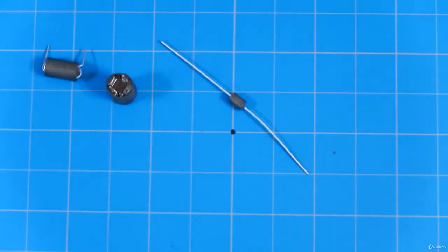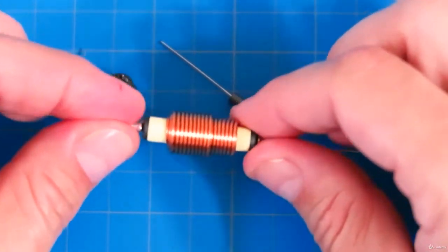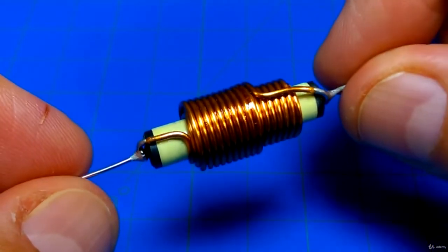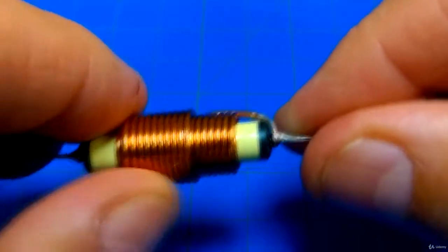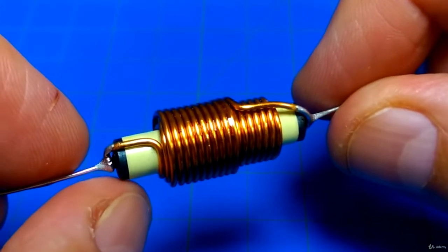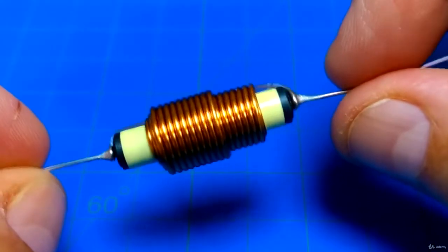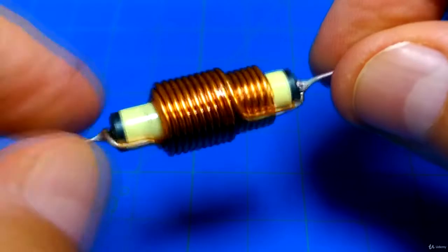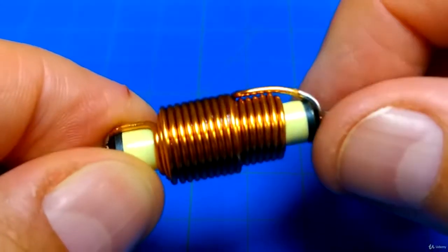Okay, so let's take this out and look at these all zoomed in so you can see what we have. This right here is an inductor, and this is pretty cool. The first thing is that the center of this is made out of iron or ferrite, powdered iron, and it has certain magnetic properties that increase the flux linkage and make this a better inductor. Then you can see the wire comes in here, the lead, and it goes to this wire here, and it's wrapped around here so many times.